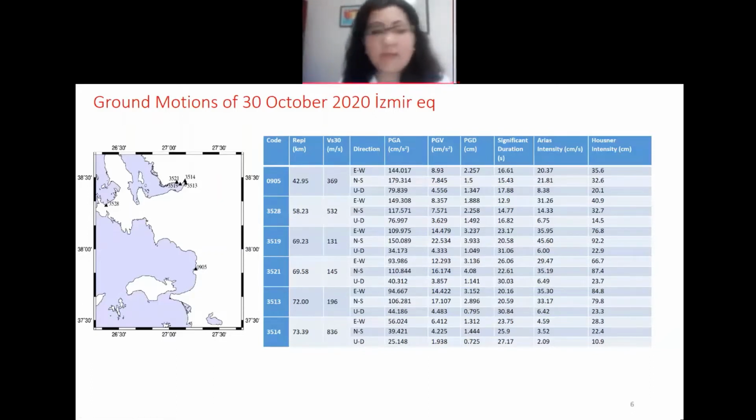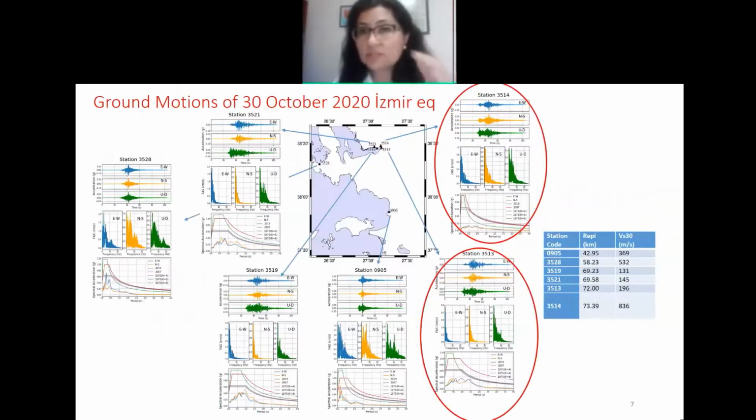We do not have really high ground motion values when we look at the peak ground accelerations, but we still have some signatures of the event. The highest is in Kuşadası, about 0.18 g, while we have lower values within the Izmir basin here. But I don't want you to suffocate in numbers. What I will focus on is the corresponding ground motion effects, let's say the signature.